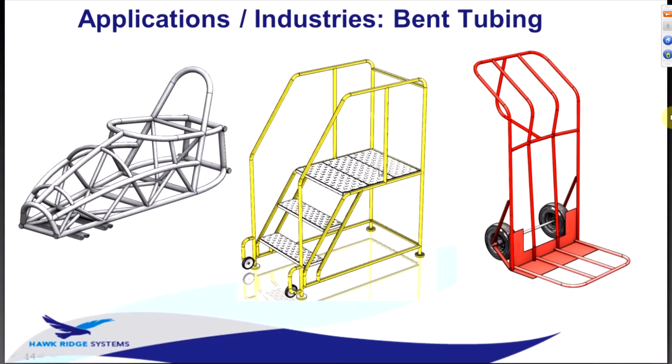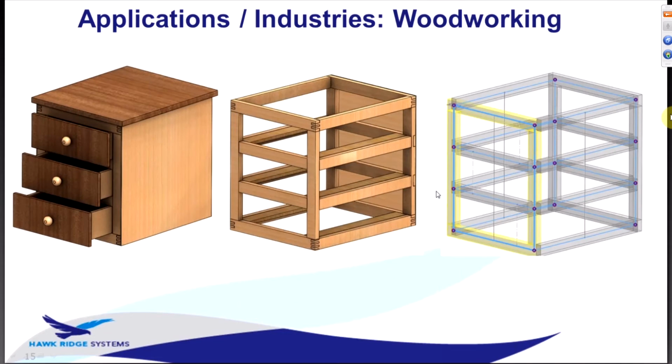You can also create using the weldment tools because again, we're just creating a line layout and then essentially sweeping the profile of our choice across that layout. And really it's the automatic trimming and automatic cut list generation that's going to be saving us a lot of time. And then even more outside the box, we can even use weldments for things like woodworking.